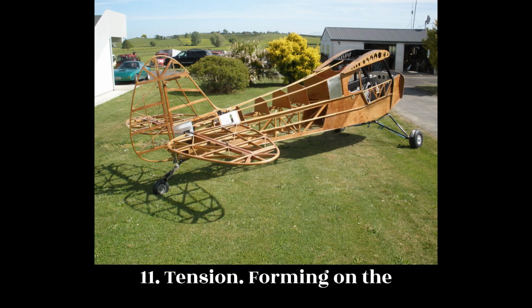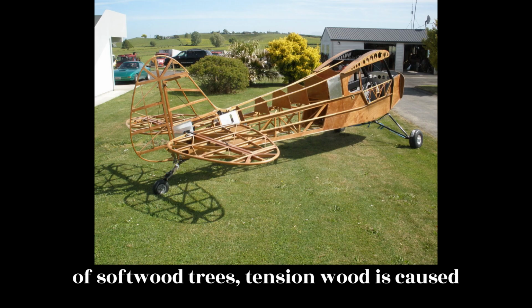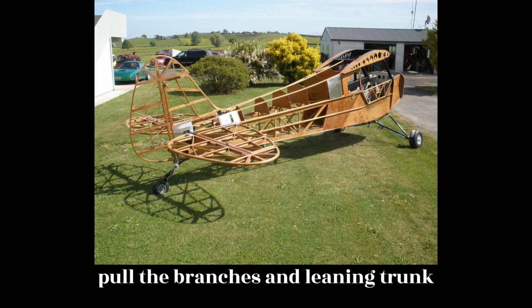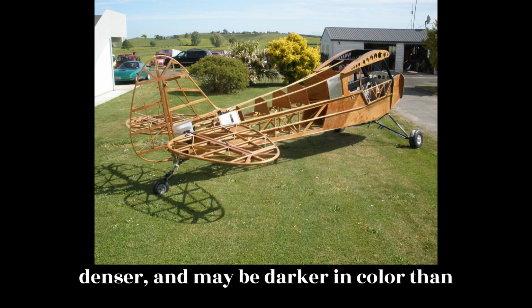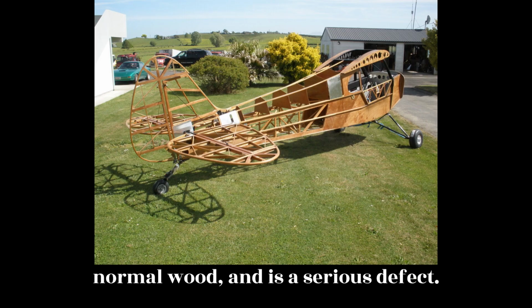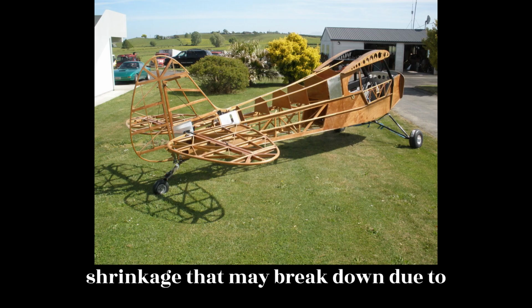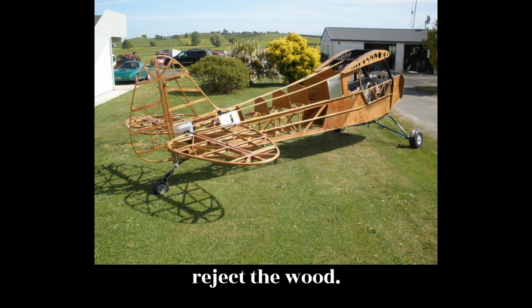11. Tension wood. Forming on the upper side of branches and leaning trunks of softwood trees, tension wood is caused by the natural overstressing of trying to pull the branches and leaning trunk upright. It is typically harder, denser, and may be darker in color than normal wood, and is a serious defect, having higher than usual longitudinal shrinkage that may break down due to uneven shrinkage. When in doubt, reject the wood.